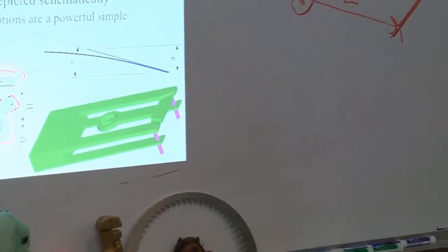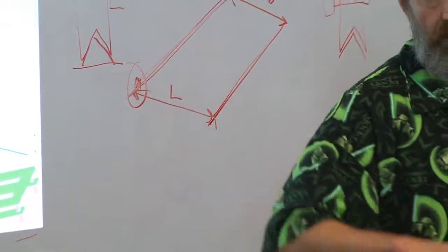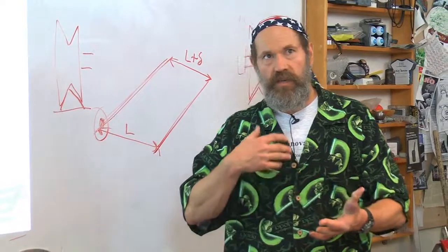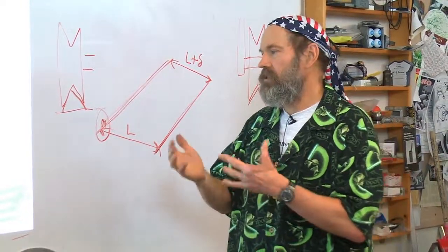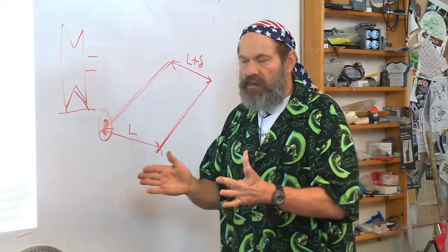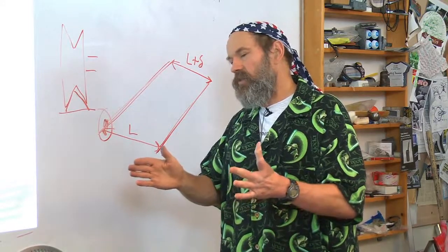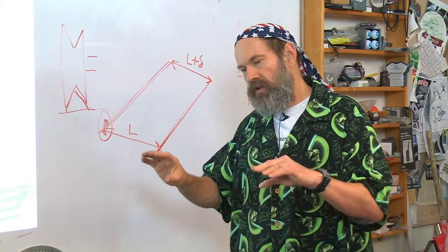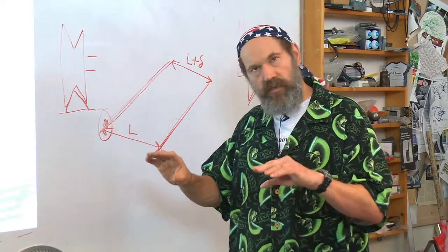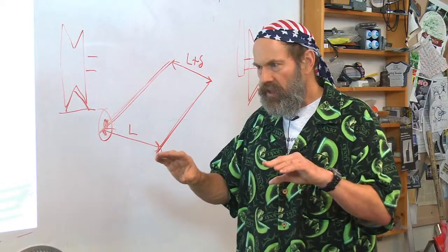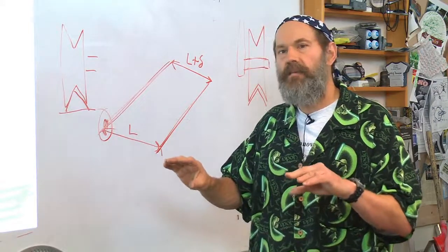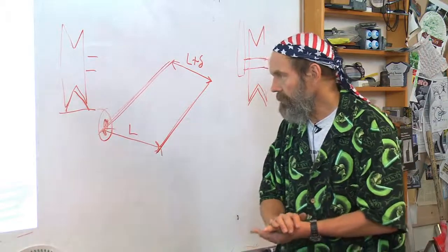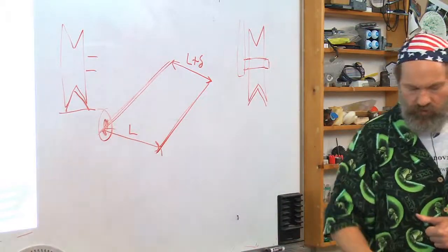So when you're designing a machine, you can start to think about the functional requirements for the machine, what does it require of me? Then you can use your analysis to say, here's the spacing between my bearings, and I'm going to make them a little wider spacing because I have the distance. Because I know I'm going to have some clearance distance between the bearing and the structure, it's going to make a smaller angle to give me less of an Abbe error at the action point of the machine. Very, very, very powerful tool.